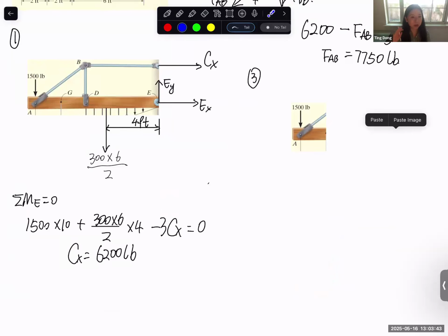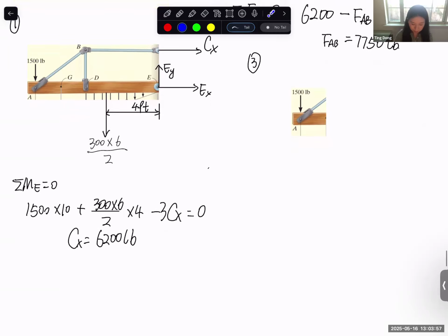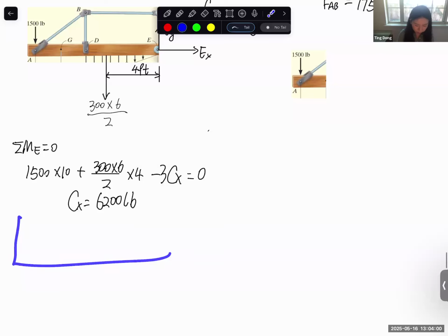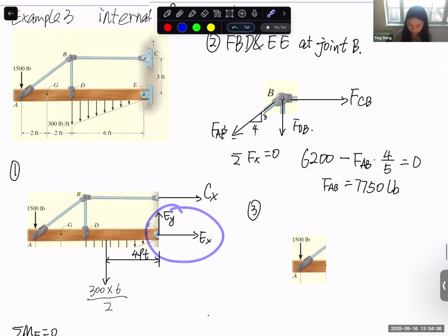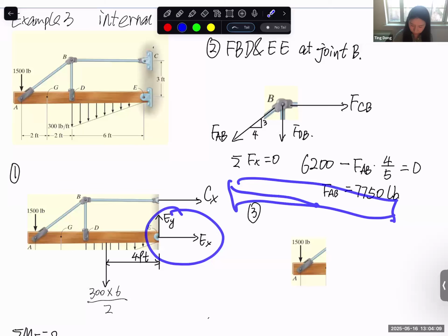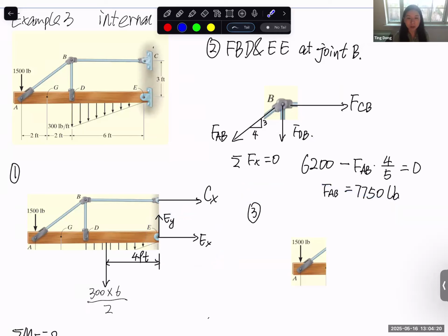And of course, I see very frequently in the exams that some students, whenever they have the free body diagram of a certain structure, always use three equations: two force and one moment, or one force equilibrium and two moment. They always calculate the whole thing and end up wasting a lot of time. We only have 2 hours to solve 4 problems in the exam, and I saw very frequently that they have force in X and force in Y, extra steps to calculate these parts, and also the force in the Y direction, an actual equation to calculate BD. And in the end, you will see that you won't need any of this.